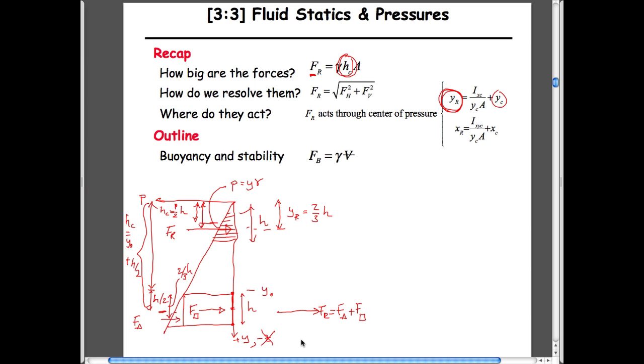So at depth, this is the pressure distribution without the triangle on it. This is the pressure distribution with the triangle on it. And so now, if you look at where that pressure distribution will balance on this point, right? This is the pressure acting horizontally. The balance point for this, well, certainly if it was for this, it would be right in the middle. But when you add this additional pressure distribution, it's slightly to the left of that, right? Slightly down from that. So that's the rationale. So you can use these expressions always for the cases that we'd like to look at.